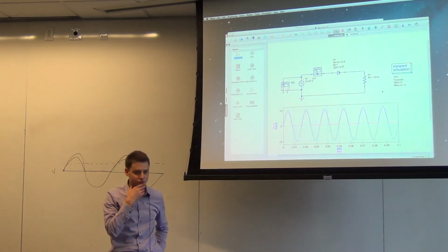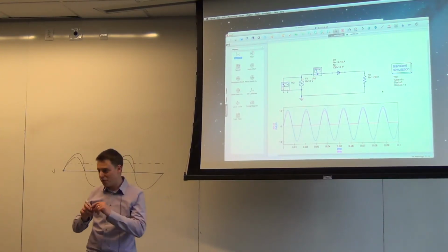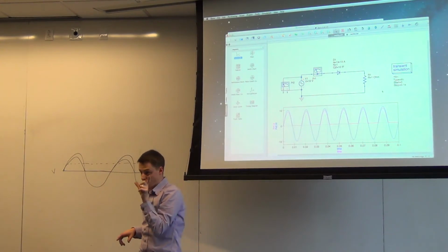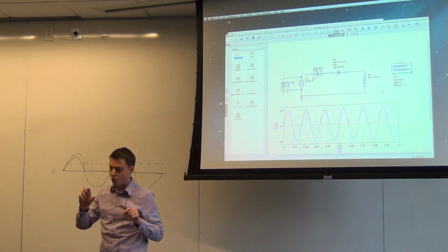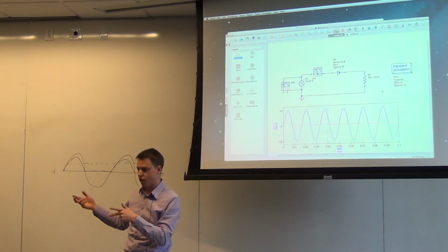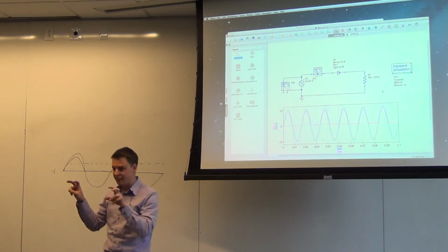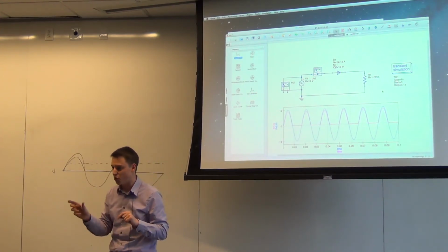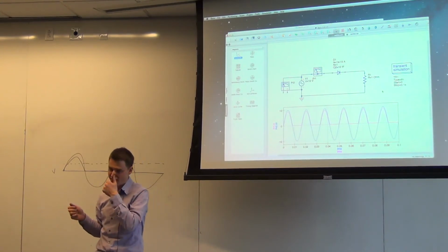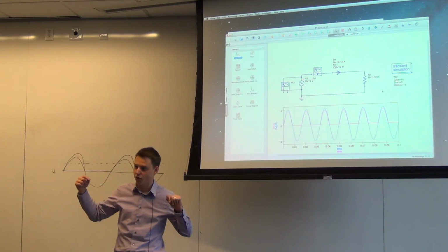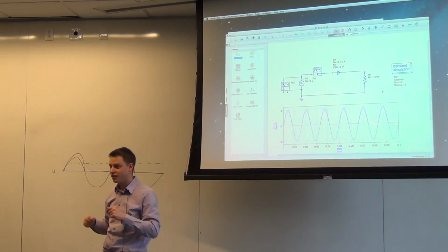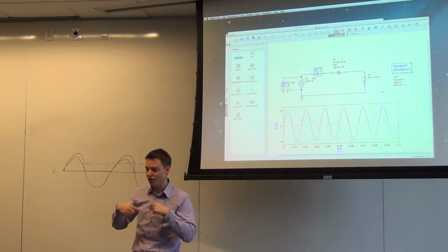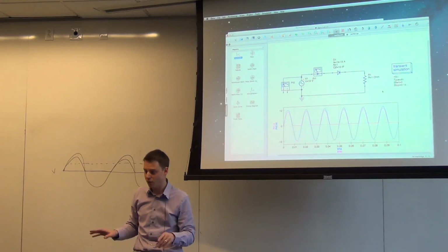So a real diode. I mean, there are two things here. Ideal, I would mean a lossless diode that just lets current flow in one direction, and that would give nothing here. Yes, real diodes will have a voltage drop, but what people call an ideal diode is something governed by Shockley's equation, which has a voltage drop to it. So when people talk about what an ideal diode means, there usually is a voltage drop across it. And real diodes are even worse than that. Back current can flow, the current can flow the other way. There's breakdown voltage, all those other things that have different effects, and aren't perfectly modeled by this equation either. Don't worry about it yet, but you'll work through that on the first problem of the next homework, so it will all make sense, hopefully.